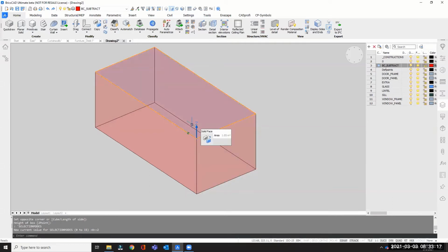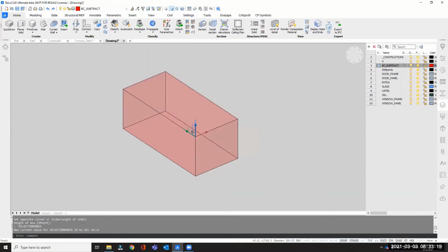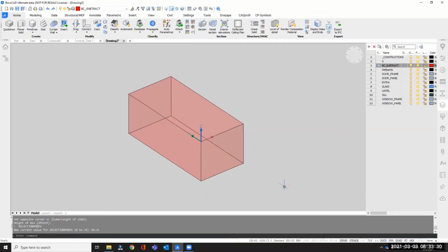But let's say you have a wall that's, let's just say, 1,000. So your subtracting solid is only 600. So it's not going to punch through that 1,000 wall. So that's the importance of this subtracting solid. So just make sure you are familiar with this. This might be a question for you when customers are trying to create their own components. Sometimes just tweaking the thickness of your subtracting solid is already the solution to the issue or the problem that they're facing. So just remember that.